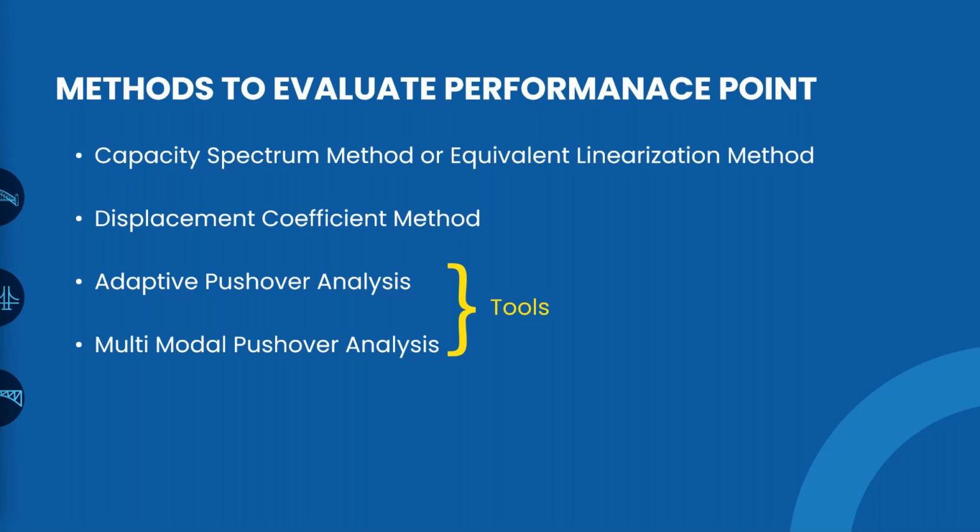Similarly, there is multimodal pushover analysis, where multiple modes, or the multiple eigenvectors of one particular structure, are considered, and a linear combination of these modes is done, and the loading pattern is applied on the basis of the linear combination that we are getting.